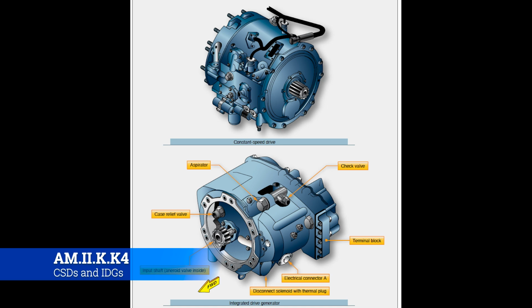The reason is pretty simple. The engine doesn't necessarily stay at a constant RPM all the time. It'll go up, it'll go down. Think about whenever you're taking off, you firewall the engine, it goes up, but then you pull it back to a cruise power setting. And even more so if you're talking about helicopters, or an aircraft like a fighter plane or an air show demonstrator, something that has to constantly make throttle inputs on a regular basis.